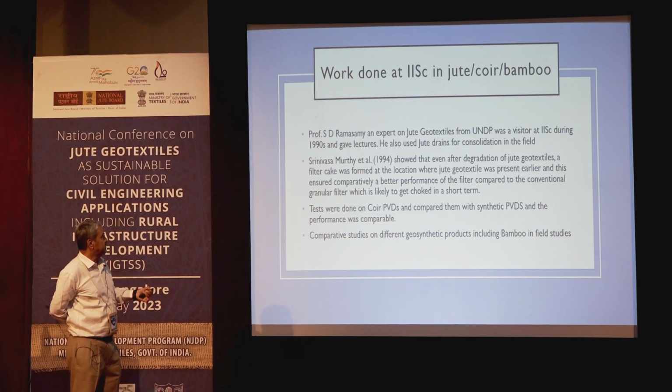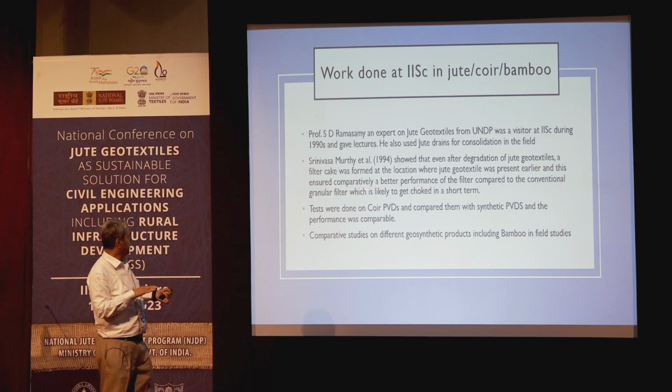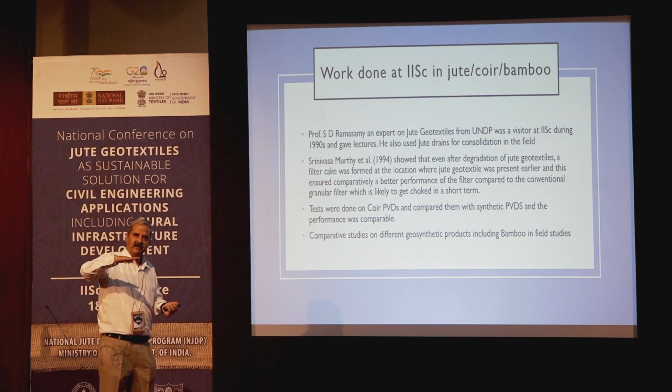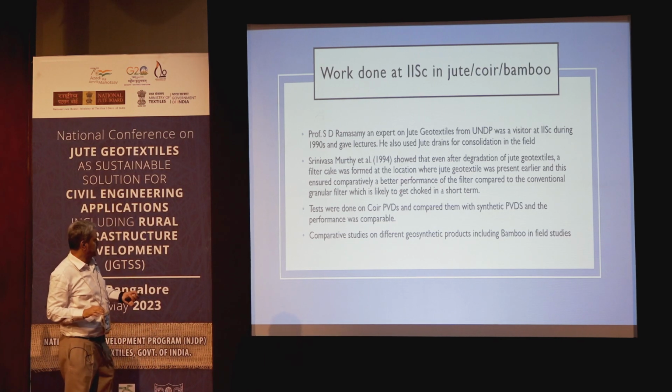In fact, our colleague Srinivasmurthy showed that even after the degradation of geotextiles, a filter cake is formed at the interface. That's another interesting thing, that normally you saw the mixing of things, but when you have a textile, the cake, that filter bridge, gets developed on the top of it. And we also did, that I'll show how it is.